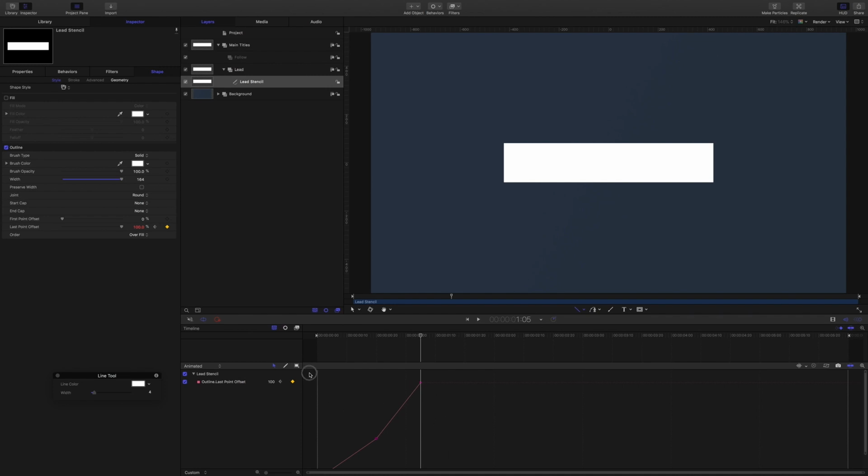Then in the keyframe editor, let's drag to select the curve, right click, choose Bezier for the interpolation, and right clicking on these handles, we're going to break the tangent wherever we get the option to do that. I'll just fit these curves into the frame. Okay, so we want to grab this handle here and pull it down, and I'm holding the Shift key so I can pull the handles straight. Let's pull the handle further this way so it runs very close to the bottom there, and we'll grab this handle and pull it in and have it running straight up and down, and this handle up.